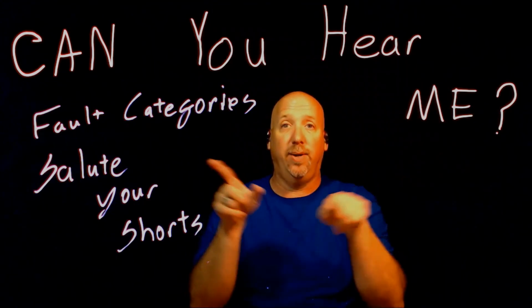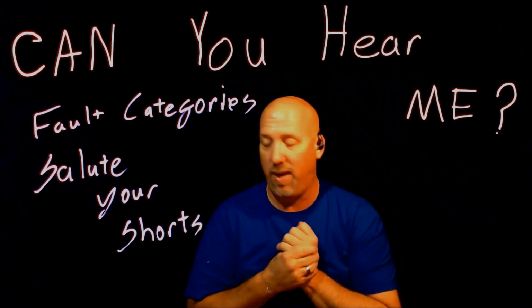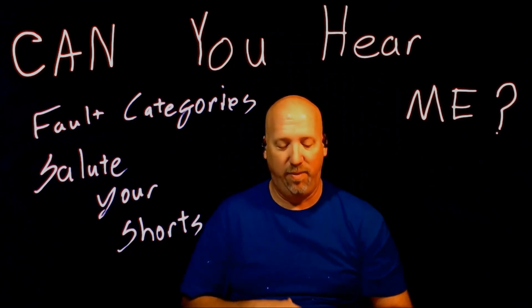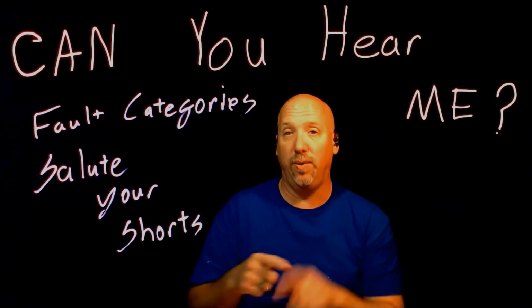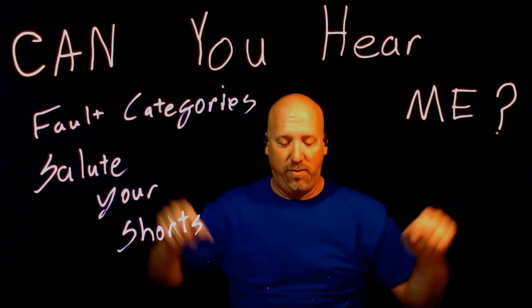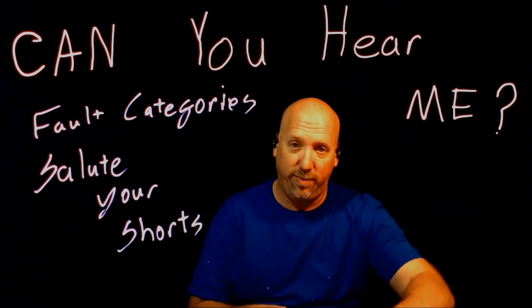For star networks, you want to disconnect the central splice or column that has the jumper legs to it to find the short. Now simply disconnect any of the modules on that leg. If the short is still there, you have a wiring fault. If it's not, you have a module fault.